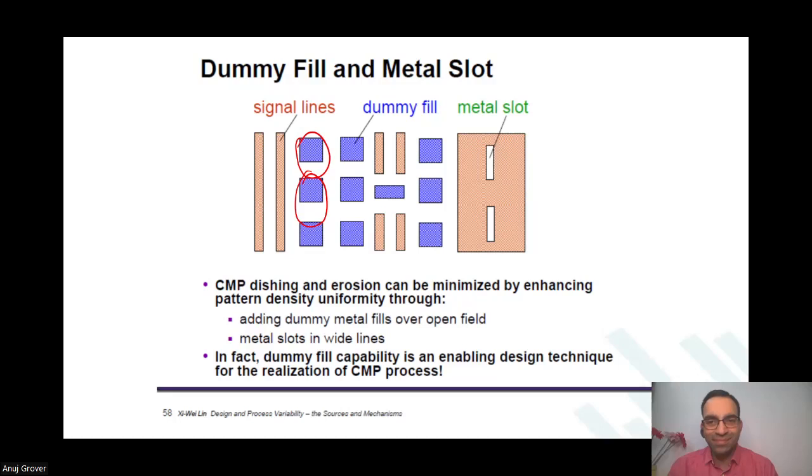But I can include this capacitance in my extraction itself. Can't I do that? So the dummy fill stage is at the fag end. Just before you enter the fab, dummies are filled at that time. Dummies are added to the layout at the last stage, before fab out, before fab in, let us say.